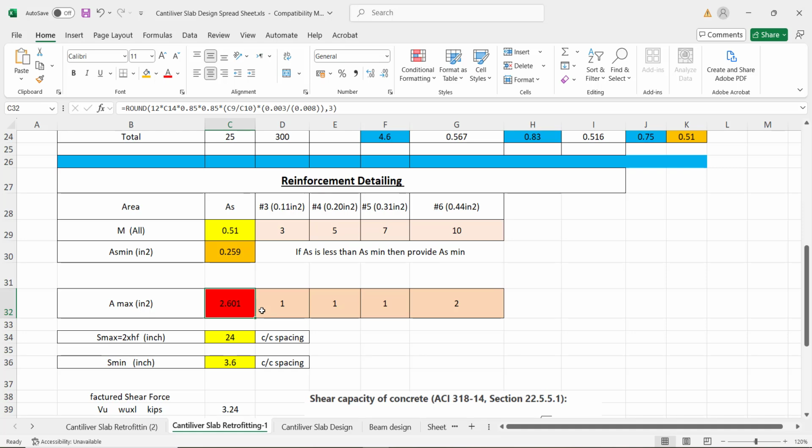The steel has this beauty that yielding should start before the concrete crushes, so that the structure can give you warning. There are some hair cracks or small cracks. It means that the structure is going to fail, but it is giving you a warning: please save me, because I am going to fail.